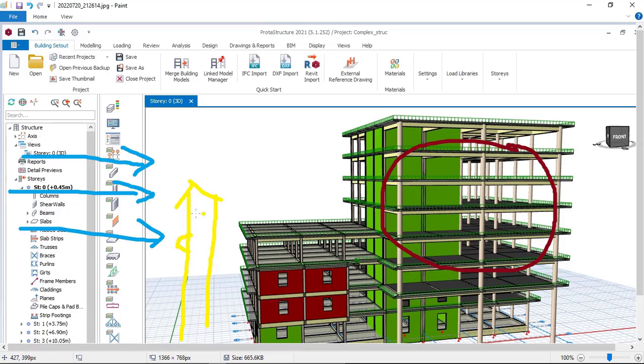Now, this software is asking you what is the height of this building right now, because the software knows that if the height of this building is very tall, like this, when the wind blows right now, it will not come directly on your structure. It will have to hit this already existing structure, or this obstacle, which can be a tree or anything. We first of all have to break this wind speed of 25.75 meters per second.